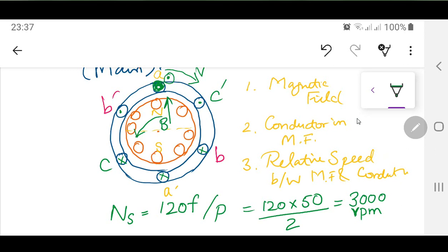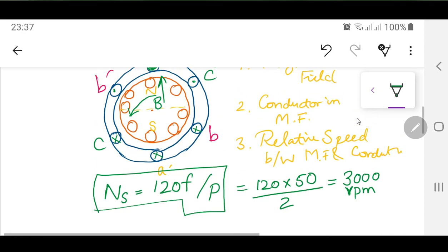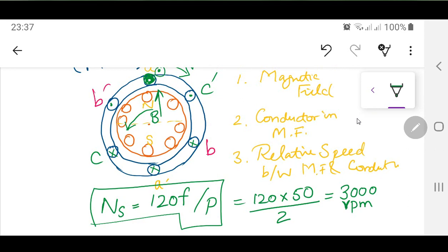And certainly, as this formula actually tells you, you are going to have your speed and poles in an inverse relationship. So this is Ns is equal to 120 F by P. If you just rearrange this, you can find out that your frequency is directly proportional to your speed, and inversely proportional to the number of poles as well. So you have Ns is equal to 120 F by P. So this is a simple synchronous generator producing the 50 Hertz output waveform from the stator. So A, B and C phases are going to produce a 3-phase supply out of it.